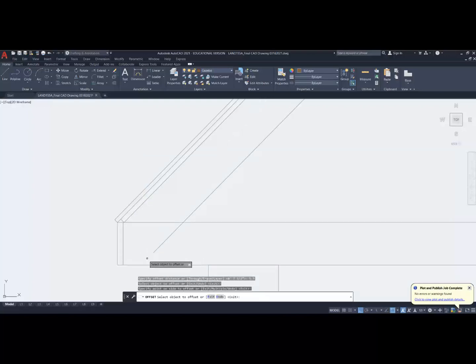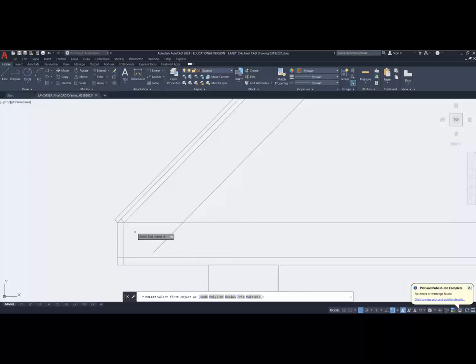And here I'm going to provide a cut so these things don't come straight down and go below the fascia level. So typically the joist will end about 1 inch offset from the bottom of the fascia board. So I'll draw that here. And now I can fillet this corner. And this will end right at this line. So the actual joist itself, and I'm going to extend this down here.